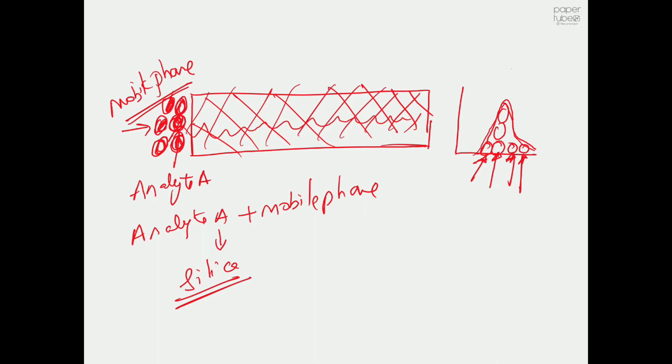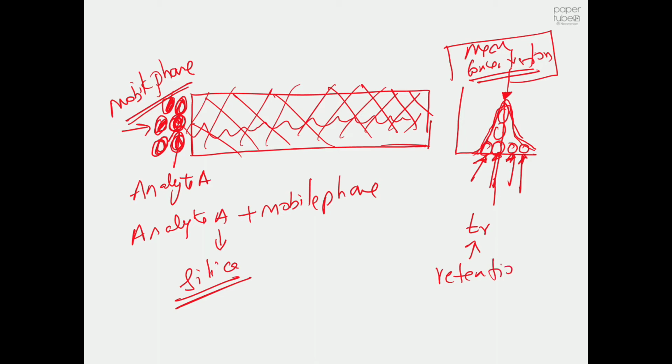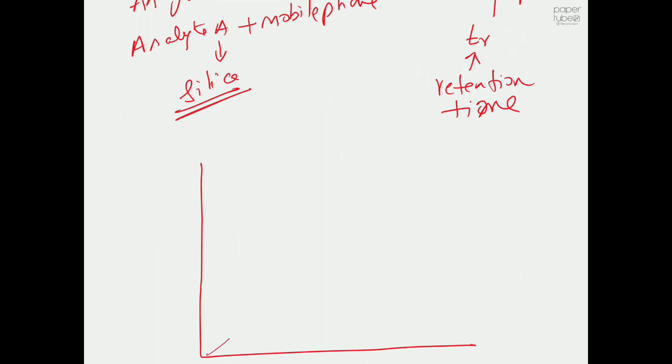What we call the retention time is the time taken by the molecule to reach the column exit. So wherever you see this mean value, mean concentration, the time that corresponds to when the concentration in the Gaussian peak hits the maximum will be your retention time. Your experimental outcome is always a Gaussian distribution.